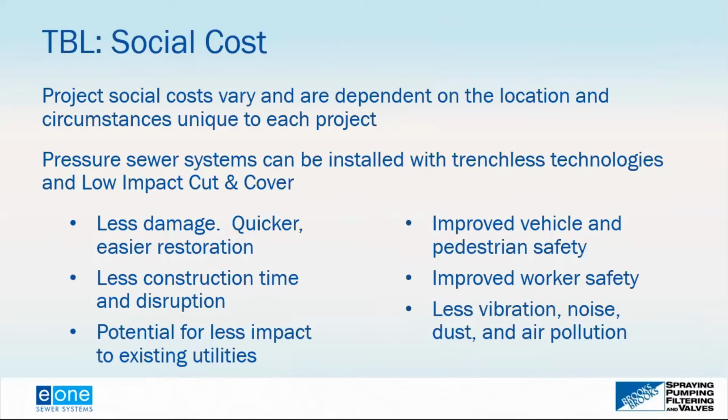The project social cost will vary depending on location and the circumstances. It's very unique to every project. But generally, when we look at the advantages of social cost for a pressure sewer system compared to a gravity sewer system, a lot of it comes down to what I've already mentioned, the ability to use horizontal directional drilling or low impact cut and cover. With a pressure sewer system, you have less damage, quicker, easier restoration.